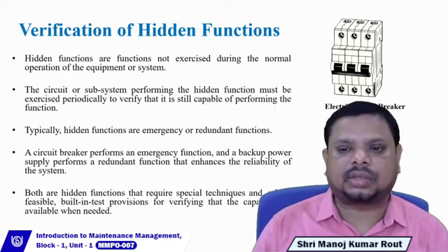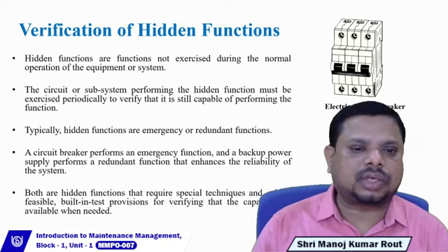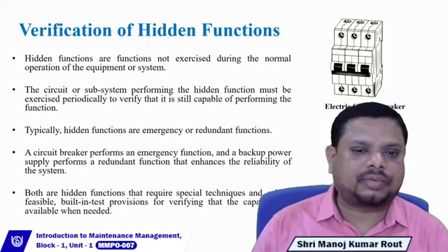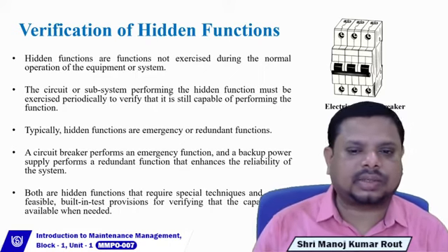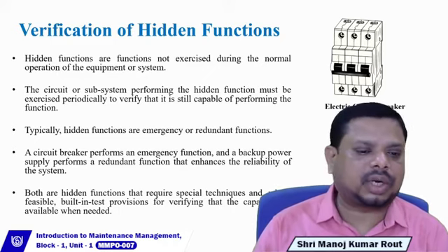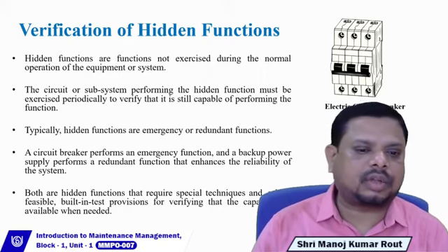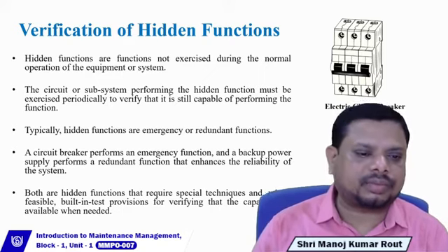In operating various complex machines like CNC machines and lathe machines, they can use power levers. If you find any kind of difficulty, you can directly put the power lever down to the off level so that the entire process stops and the machine will be safe. And those who work on that particular machine will also be safe.